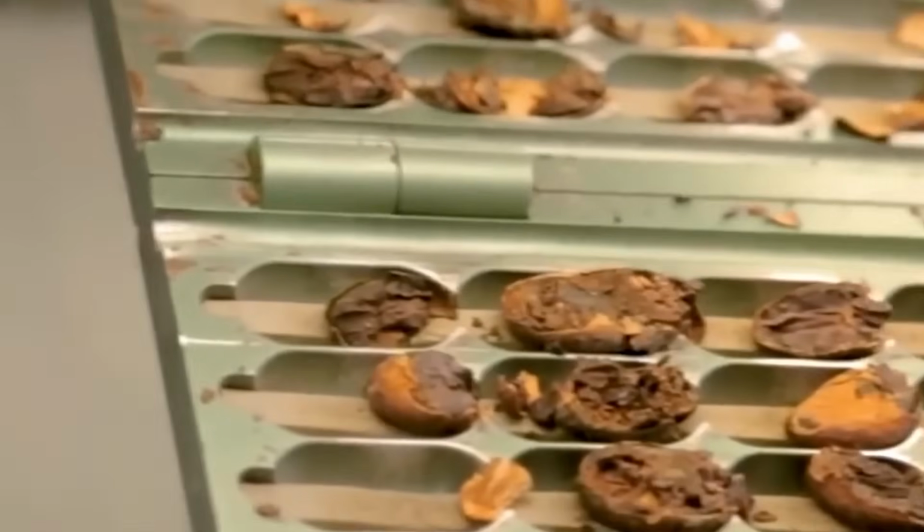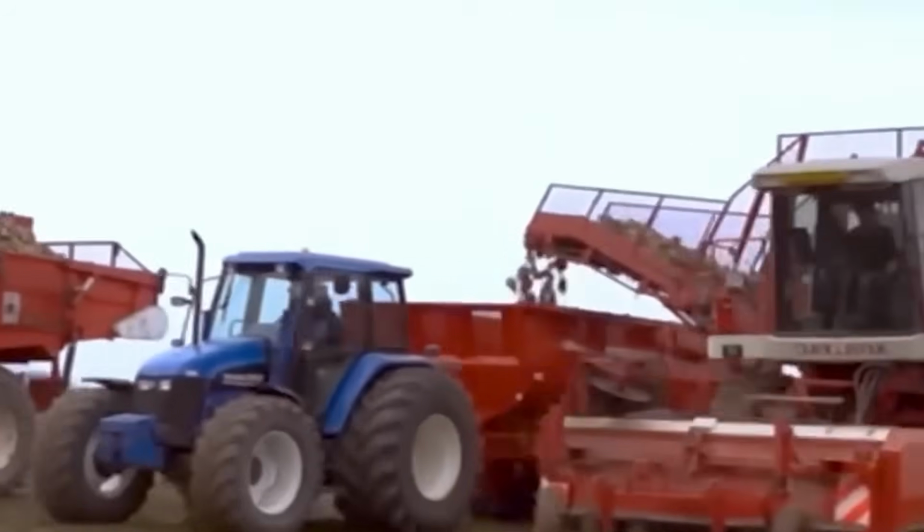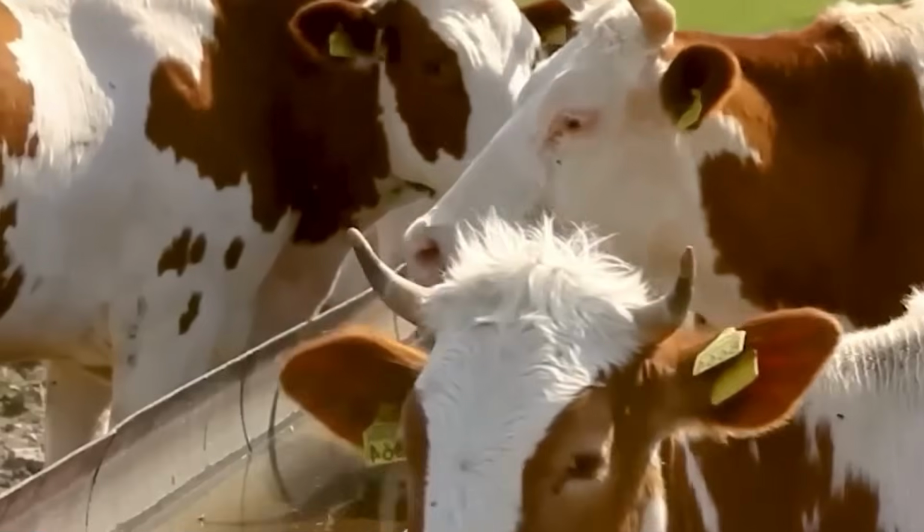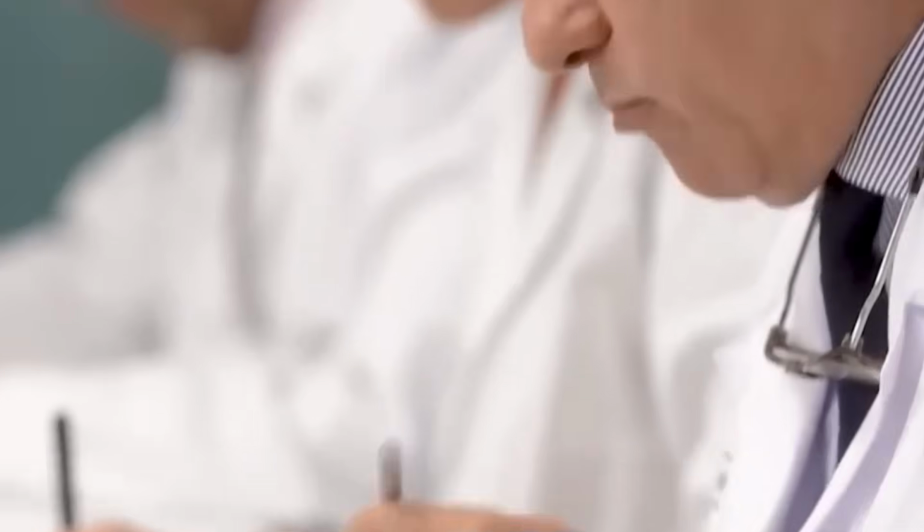Each component is produced under tightly controlled parameters using fully automated equipment integrated into a high-throughput, continuous processing line. The outer shell is made from a low-moisture, wheat-based dough formulated to bake into a crisp, blister-free wafer. The dough formulation begins with dosing refined wheat flour, sugar, salt, leavening agents, and a blend of plant-based fats into an enclosed paddle mixer. Dry ingredients are dispensed from silo systems into individual weigh hoppers with accuracy to within plus